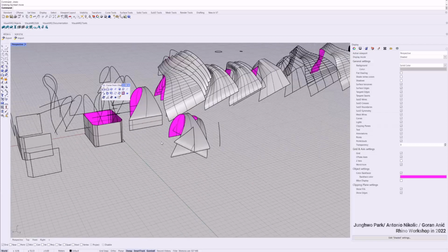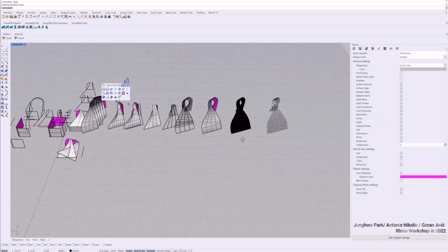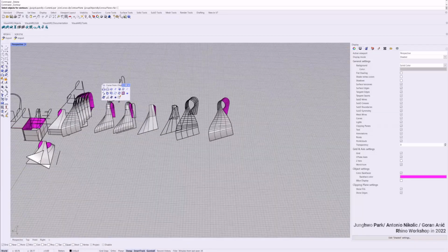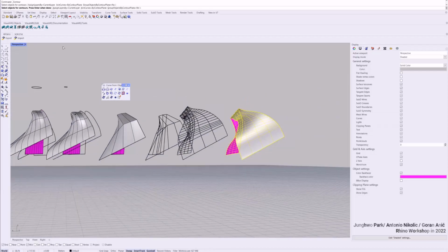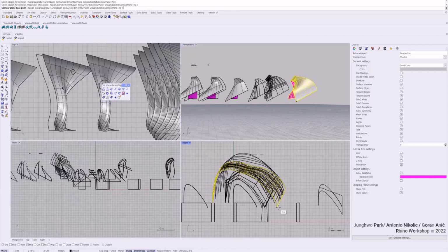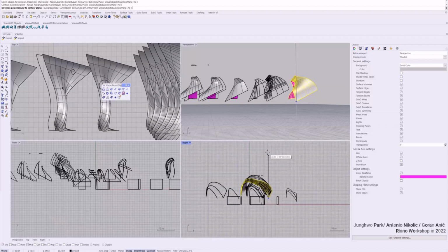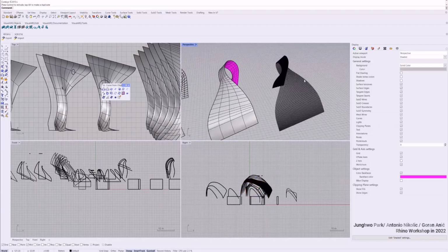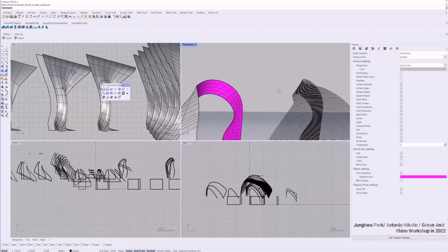Okay, very simple. What could be a very interesting tool is the contour tool. What it does is you select one of the geometries, and then you give the direction, from start to which vector you want. For me, I want to give directly up, and let me give 1 centimeter to create the contour. Then it creates contour lines of this particular surface towards the vector I gave, at a certain distance. So every 1 centimeter we get this kind of contour line.